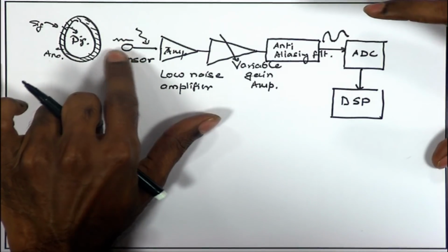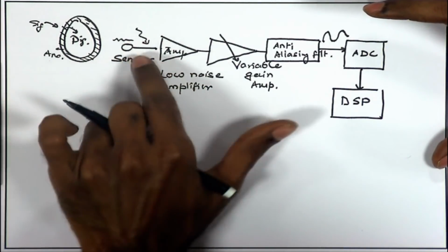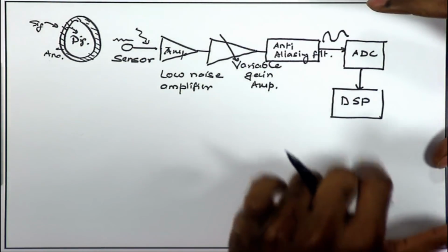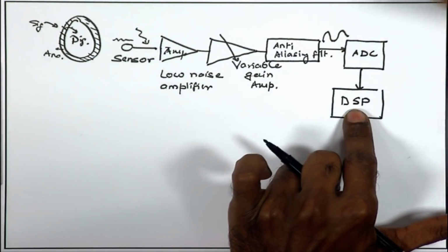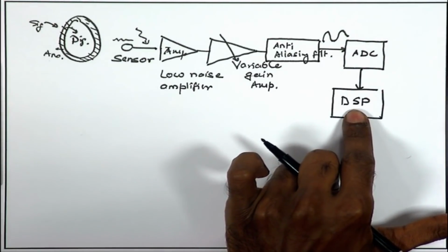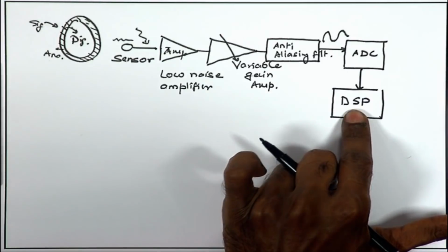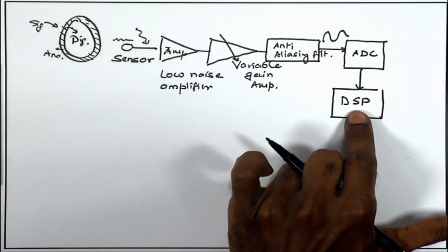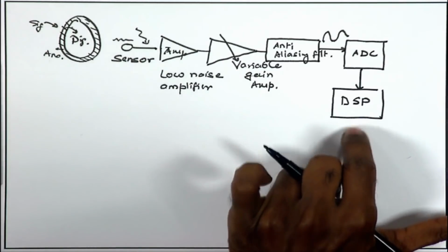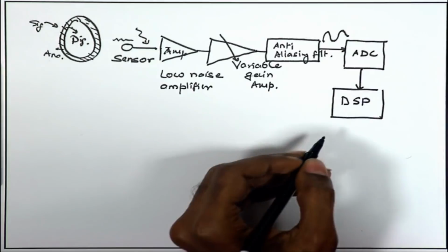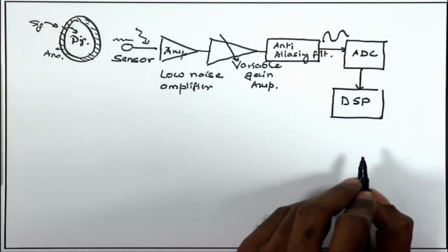We are supposed to acquire real time signals from some sensors continuously and make sure that the signal integrity is maintained all the way to the ADC while doing the analog domain processing. Following that, we need to transmit the acquired data through a wireless link to a central unit which has much more computation power, memory and resources, and is not so power constrained. So, we may need some digital domain processing before we send that data out, which helps in processing, compressing and extracting certain essential information out of the data coming from the ADC.